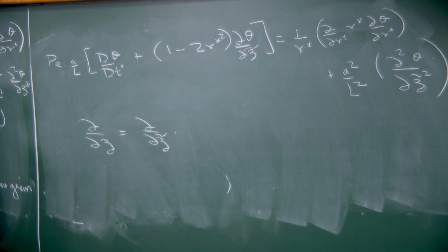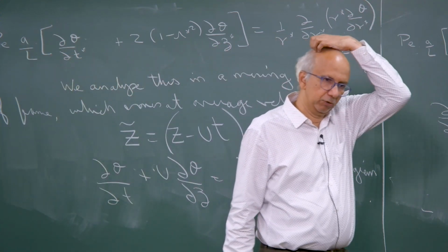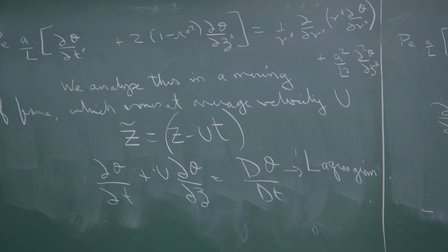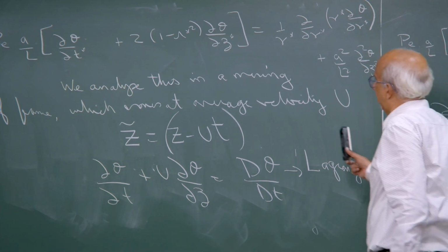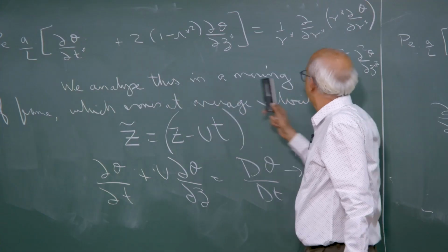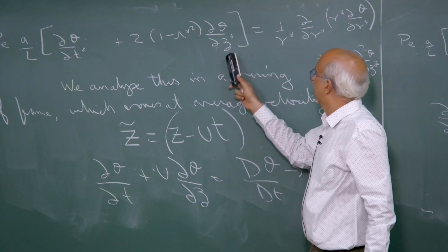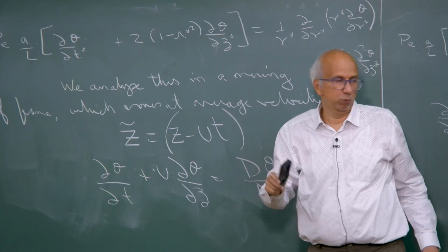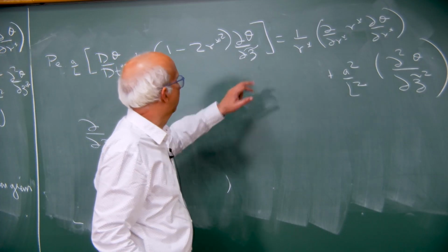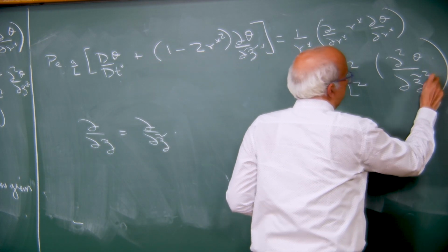That is the point. Because z tilde and z are linear, just the same thing. So, two things I have done: I have shifted from the Eulerian reference frame to a Lagrangian reference frame, so the partial derivative has become the substantial derivative. The other thing I have done is said, look, this z does not make any sense, I need to do z tilde, maybe z tilde star, because z tilde is also dimensionless.